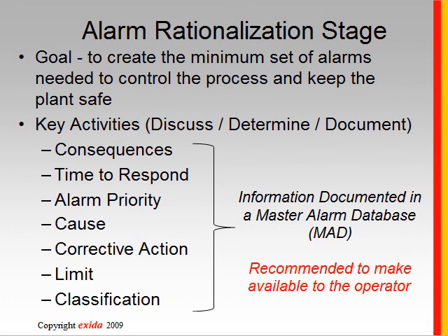And what we're going to do in terms of a workflow process is we're going to take each alarm and say, okay, what would happen if this alarm is not addressed? If the answer is really nothing, then that point should not be an alarm. If there are potential consequences, then we're going to look at those and fit them into a categorization, whether it's a low, medium, or high severity.